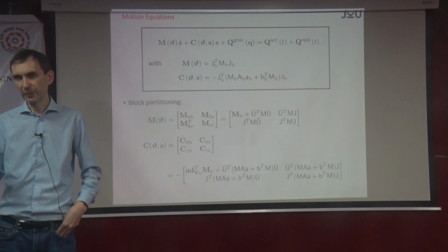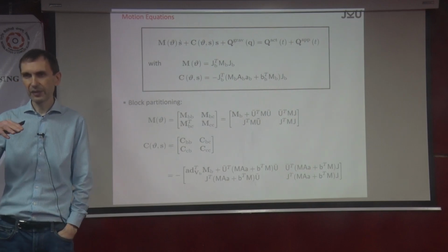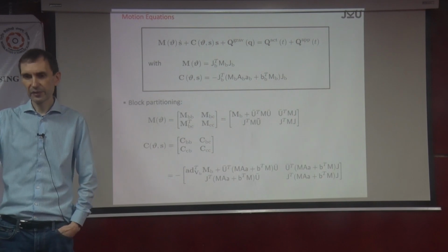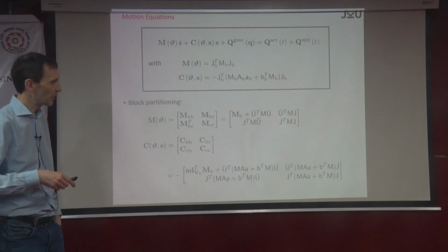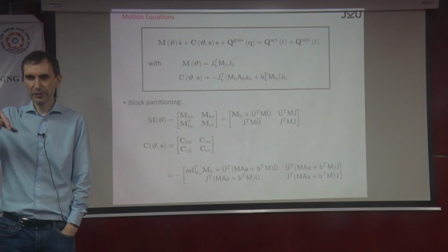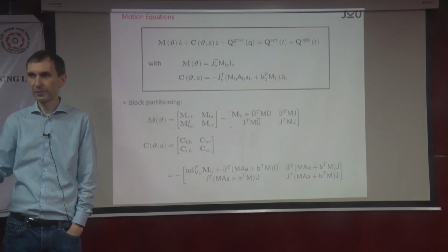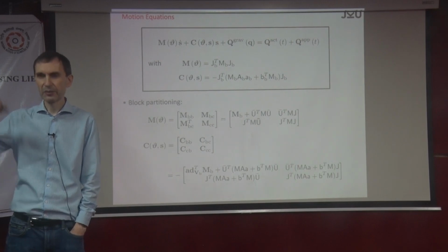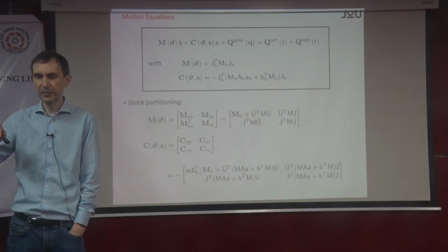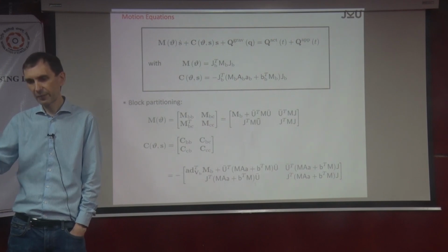Then, very simply speaking, you fit the model to the transfer function, or the frequency response, not the other way around. Of course, this depends on the pose, because when the robot is posed differently, it changes the transmission function, because it's a non-linear transmission function. That's why you have to do this again in different poses.